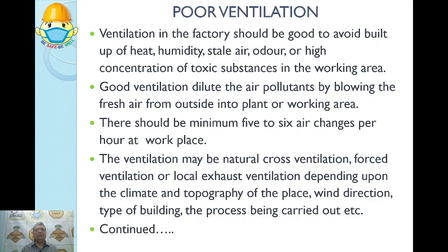So good ventilation, why is it required? Good ventilation dilutes the air pollutants by blowing fresh air from outside into the plant or working area. There should be a minimum of 5 to 6 air changes per hour at the workplace. If there is a big workshop room and you want a comfortable atmosphere, there should be a minimum of 5 to 6 air changes. Whatever the air volume is there, it should be changed a minimum of 5 to 6 times per hour.